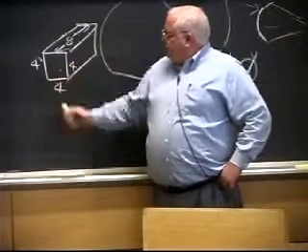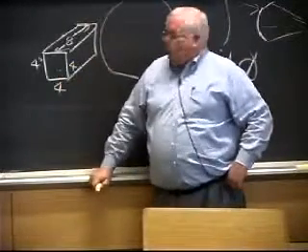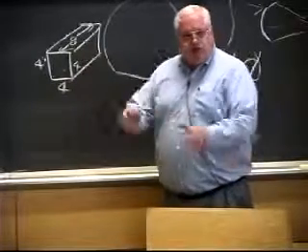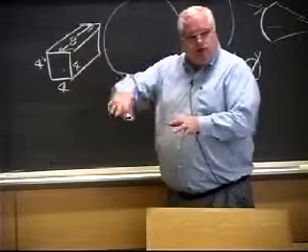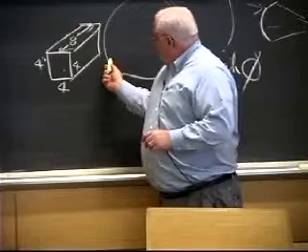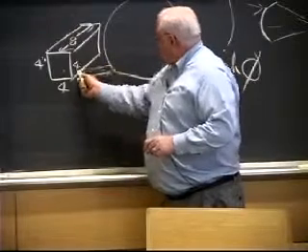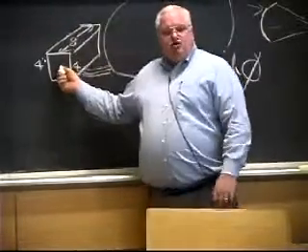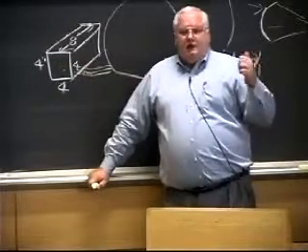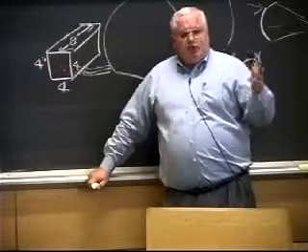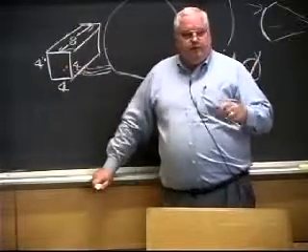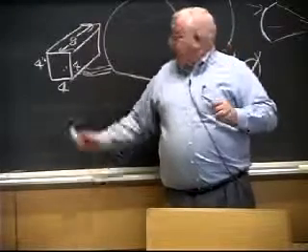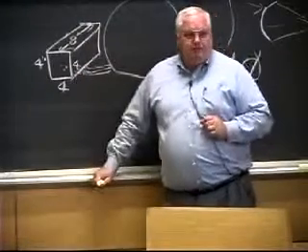They have this 4-inch square test block, so they cast the same tube in the same mold. This is just off one of the runner screws. Some of the metal goes in. You have a connection, a liquid connection or a pipe, in between. You cut this off, and you can take all your tensile specimens out of the test block. And you go to the American Bureau of Shipping Rules. It tells you you can use this.